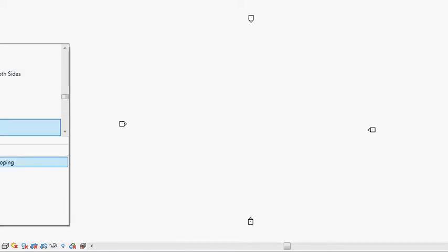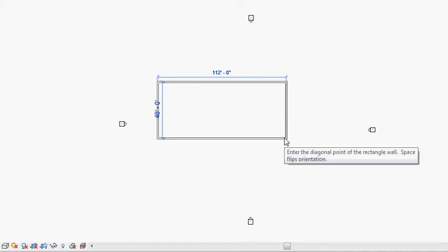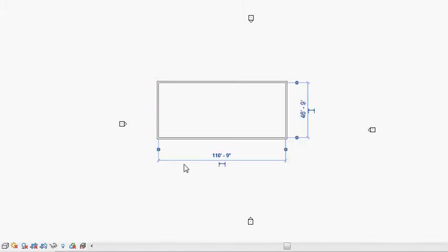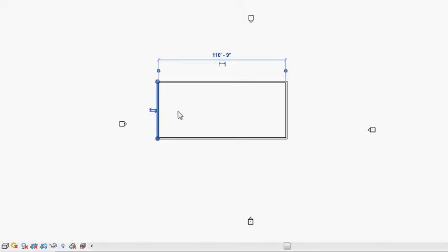Small retail space. So first I'm going to start off with my wall type, if it's going to be some type of brick or clad siding or anything, and it's going to be a simple rectangle. I'm not going to do anything fancy, just real quick. Check my exterior wall and make sure that my justification lines are in the correct location. I don't want my brick on the interior side of my wall.